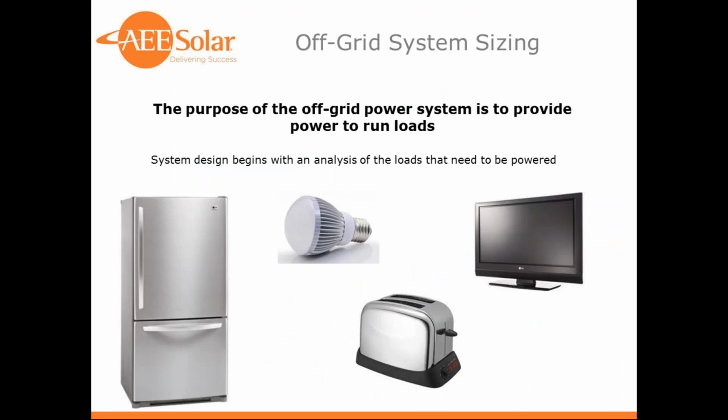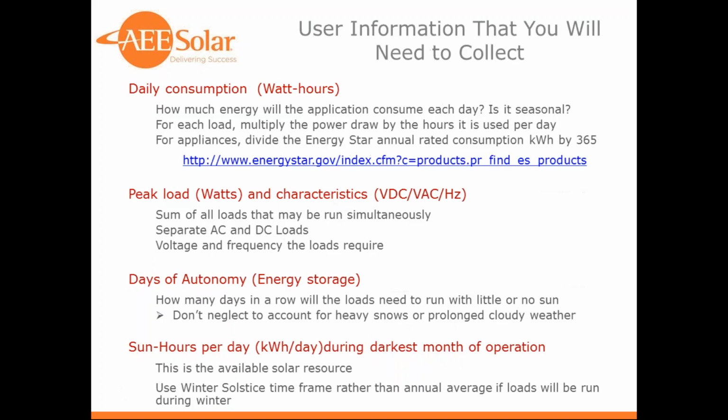So when considering off-grid system sizing, we have to remember that the purpose of the system is to power loads, not just to produce energy, as a grid-tied system would be, but we're actually running specific loads. So we need to know what those loads are, and we need to know how often they're used, how much power they draw, and we need to size our system based on that load analysis.